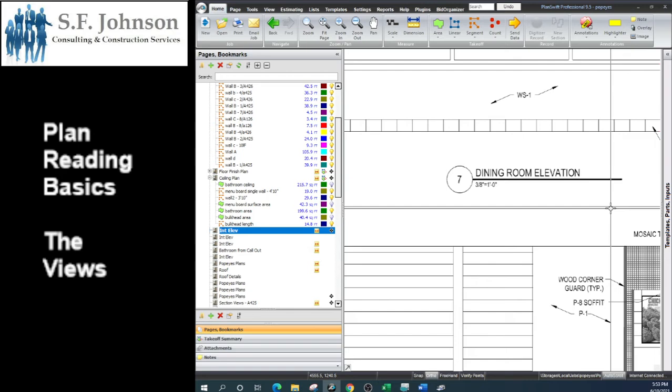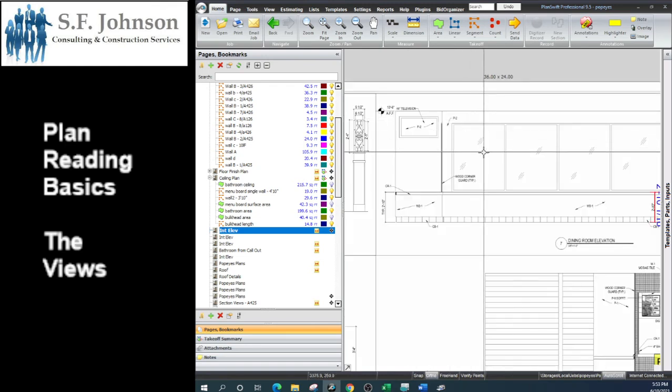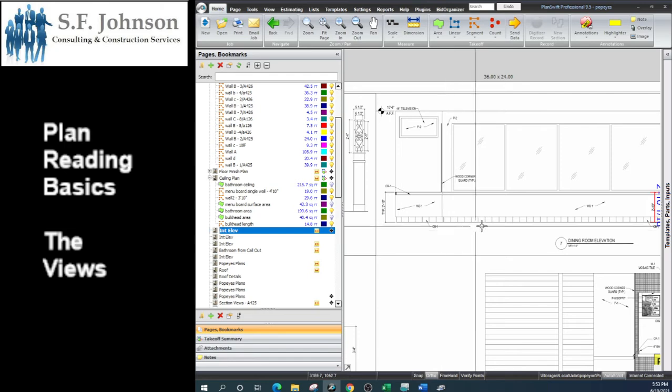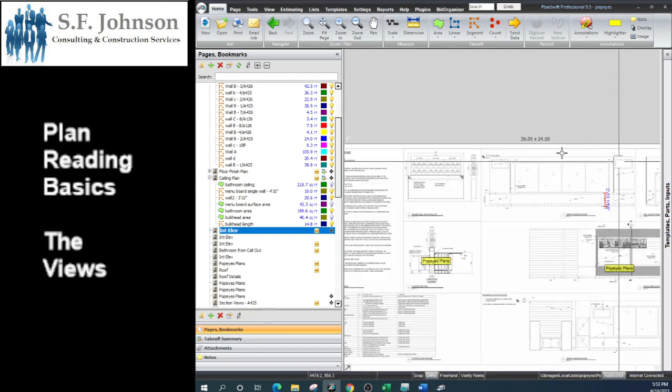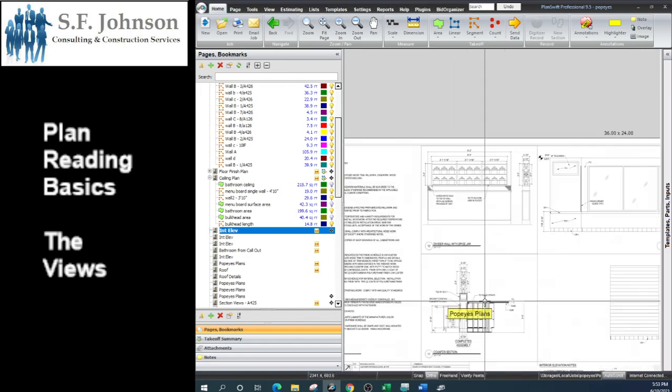Okay, so now it's showing us all our walls are built, right? So showing us where the finishes are going, where P2 is going, where WS/1 is going, where CB1 is going on that wall. So now I'm the finish contractor. I'm the painter. I'm installing some of the finish trim or finish whatever. I can make my measurements using the interior and exterior elevations.